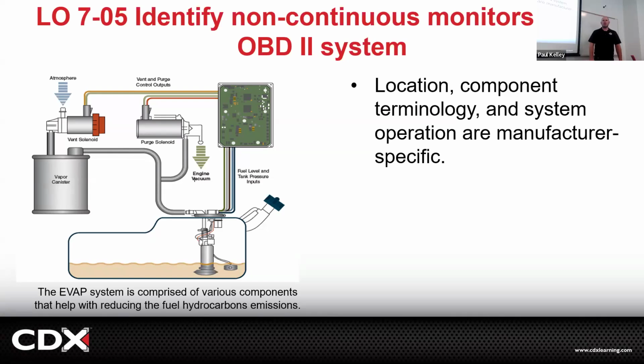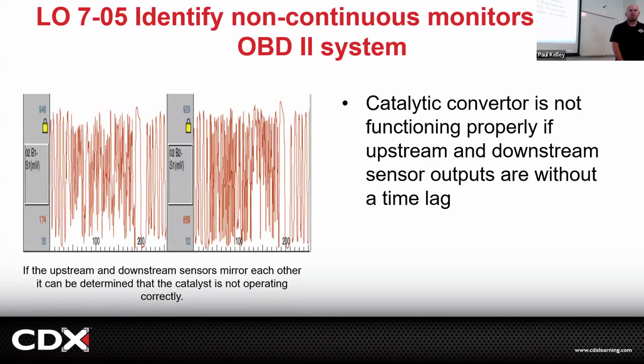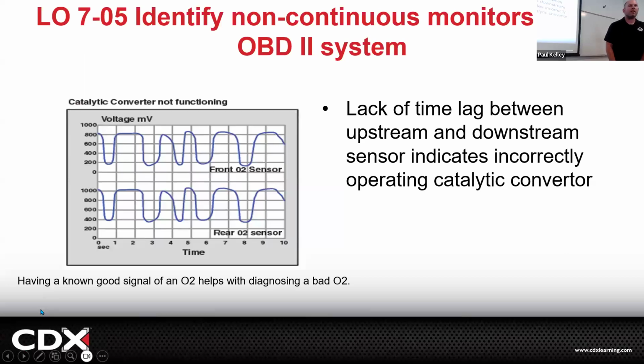Well, they can't tell it's hollowed out. Well, let me remind you of something. It doesn't look hollowed out, but you know who knows it's hollowed out? The O2 sensors report it, and the PCM's like, duh, P0420. He's like, hey, I need a smog. And they're like, you got a P0420 set. This fails. And he's like, well, my son will clear it. And I'll be like, yeah, clear.